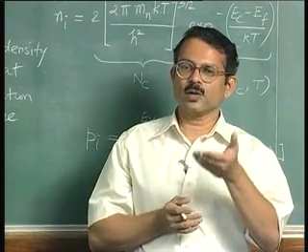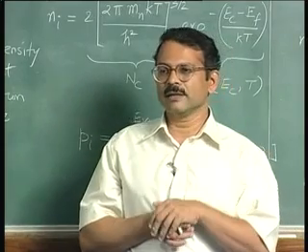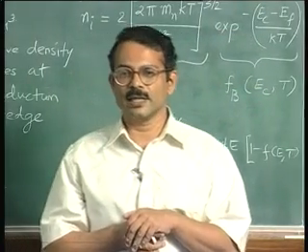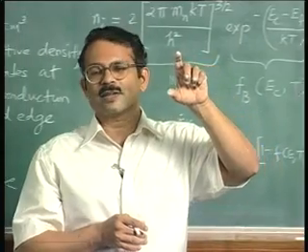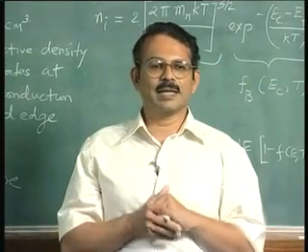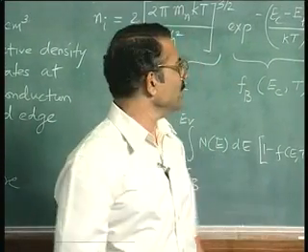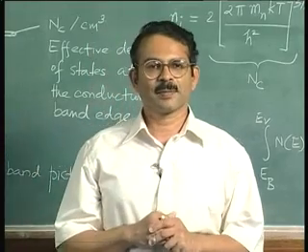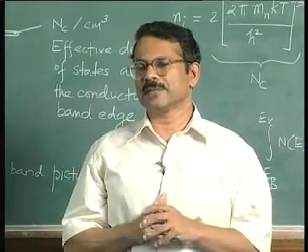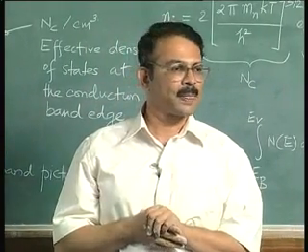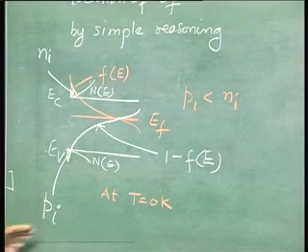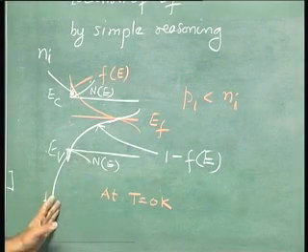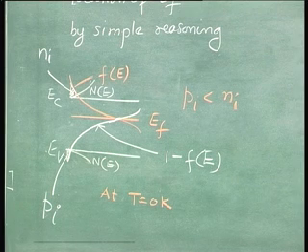0.026 electron volt. So 0.026 into 3 times kT, 0.026 into 3 is 0.078 electron volts. So you compare 0.55 electron volt and 0.078 electron volts, right? So you will always find that Ec minus Ef in a pure semiconductor like silicon and in many other semiconductors will always be more than 3 times kT at any temperature, and therefore Boltzmann approximation is valid. That is the reason why the Boltzmann approximation is valid, and that is why this effective density of states picture,